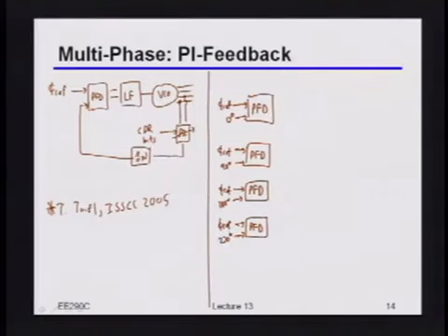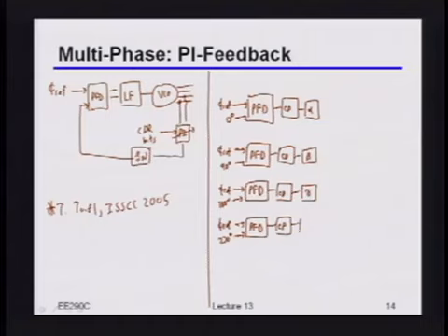Okay, well, so now if I do that, you should think of the output of the PFD as maybe including, well, let's just be totally clear, we'll add in the charge pump directly afterwards as well. And now really, if I just take those charge pump outputs, and I scale them by different weights for each one of those phase frequency detectors, and then all I do is add all those things together in the current domain.